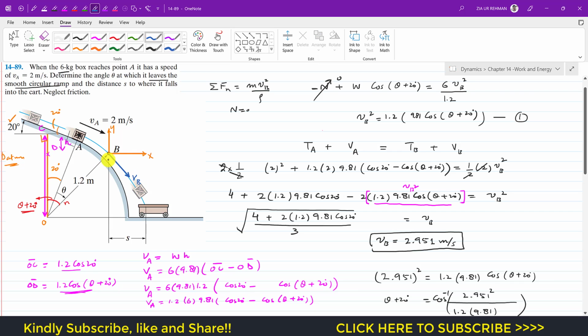Now as we can see, this VB is perpendicular to this radial line. If we draw a line from O to this point B, this VB is perpendicular to this line, and this x-axis is perpendicular to this vertical line. So the angle between these two lines is theta plus 20 degrees, as we have already discussed. Both of these angles are alternate angles.